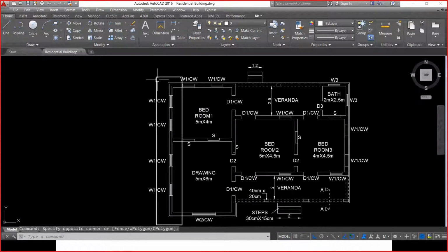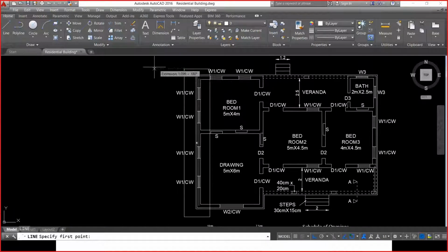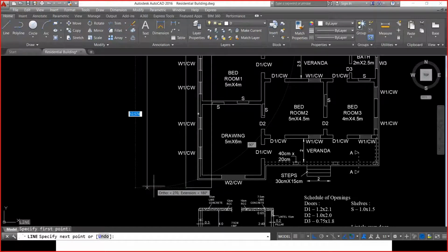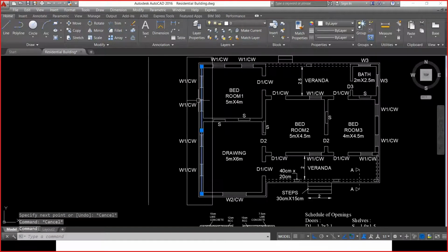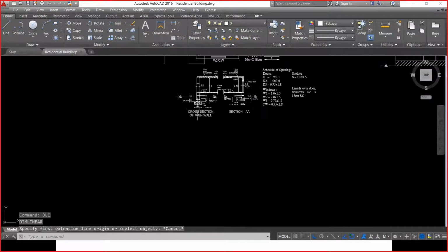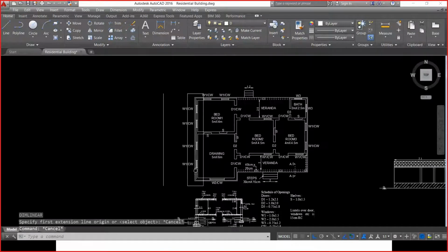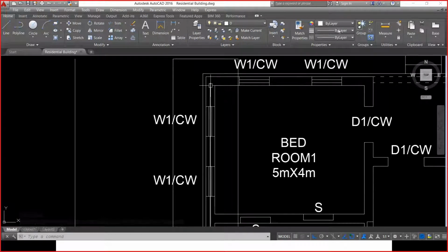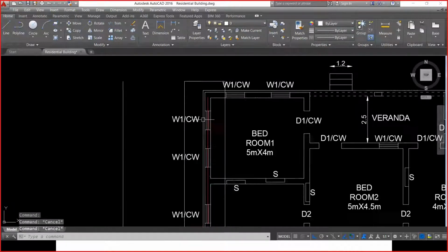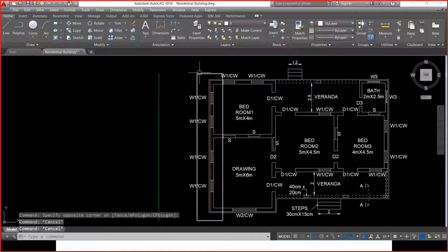in order to calculate the entire area of this rectangle, I need the full length. I'm repeating, full length is the actual length. This is not the actual length. This is just the center line length, center to center distance. But I want the actual length, multiplied by the width. Of course, I know the width. Width is 0.9 meters, and I don't know the full length, because this one which is indicated in red color is the center line length, but I want the total length. Total length is indicated in green color. This end to this end is the total length.